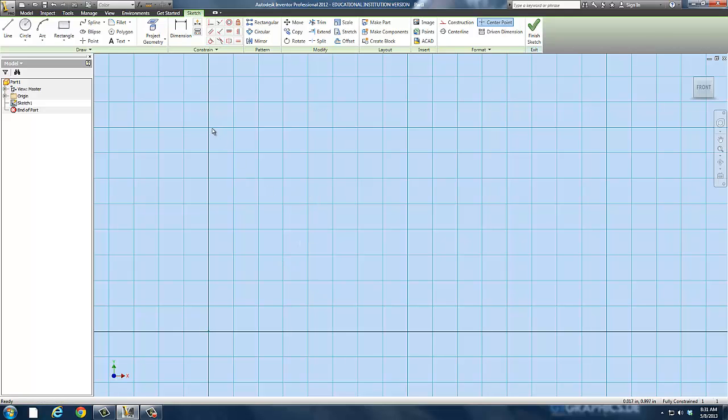Now, if you look, you'll see a slightly darker line here and here. Those mark our inches. So from this point to that point is 1 inch. And if you count, we have decimal breakdown. 1, 2, 3, 4, 5, 6, 7, 8. We get an eighth of an inch breakdown.